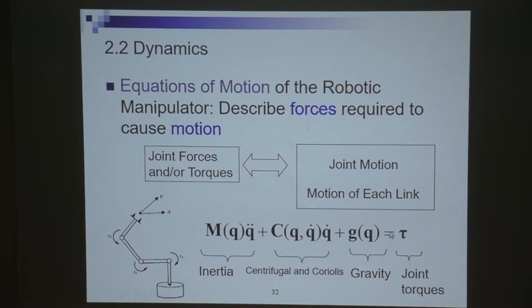The equation over here is the general manipulator equation of motion. Where you have the M, we're representing the mass, the Q over here representing the joint, Q dot, and then you have the centrifugal force, gravity over here, and finally you have the joint torque. So this is known as the general manipulator equation of motion. When we talk about the dynamics, we'll talk about that.